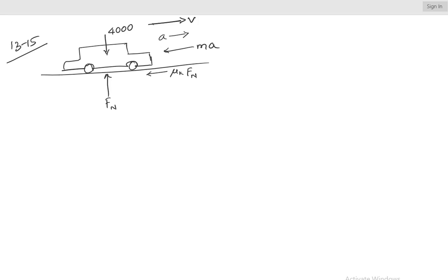You can just initially, when you're drawing the free body diagram, you can assume. Of course, it has to be a guessed assumption, but either way, the problem will correct for itself, meaning that if the acceleration is indeed in this direction, then the number for acceleration will come out positive. If it is in the opposite direction, which you will see actually is in this case, but I want to leave it like this so that you can see what happens when you make this assumption.